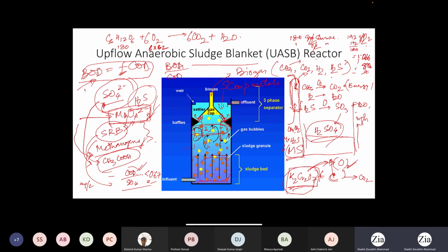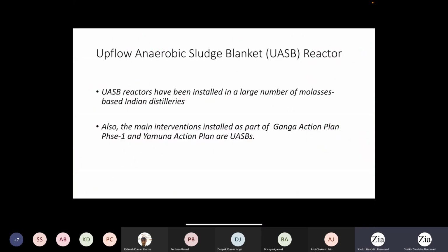And we are talking about H2S because it is one of the primary causes of failure of anaerobic reactor. So when you have a lot of H2S production, it will inhibit methanogens also. And in an anaerobic reactor, we actually get a series of reactions. In an anaerobic reactor, first all complex hydrocarbon will get hydrolyzed. So four different steps of reactions are happening in an anaerobic reactor.